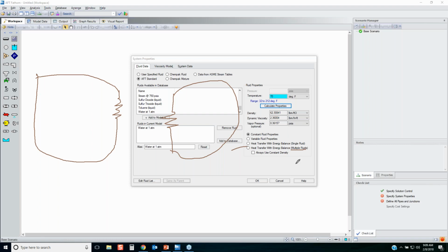The multiple fluids option is where, if both sides of the heat exchanger are fully liquid phase, and the same for their loops, you can thermally link together these two heat exchangers, which would model the same physical heat exchanger in the same model, and then you'd be able to model the respective loops in the same model itself. Maybe this is a cooling water loop, and maybe this is a hot oil loop. That's what the multiple fluids option would do for you.